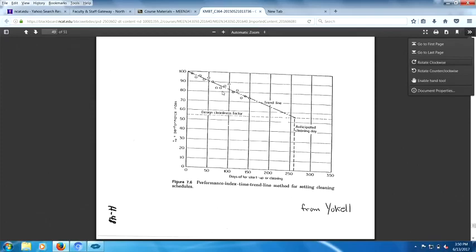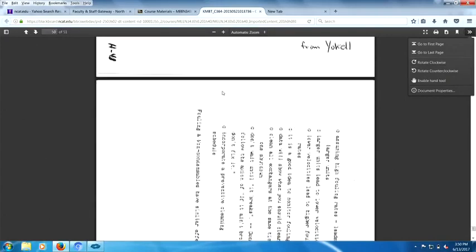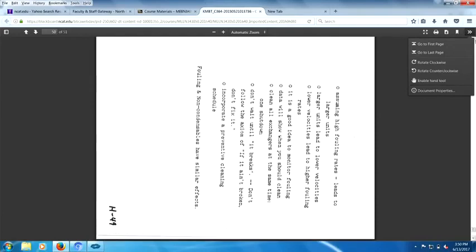So 1-2 heat exchanger: one pass tube side, one pass shell side, two passes tube side. We've already gone through that. You don't want to go to the 4 and 6 pass type exchangers. All those are channel covers really, but keep it simple, sweetheart. KISS, K-I-S-S, keep it simple. Standardized, all your cleaning methods are the same. Everybody knows how to clean. And voila, everybody likes you again.